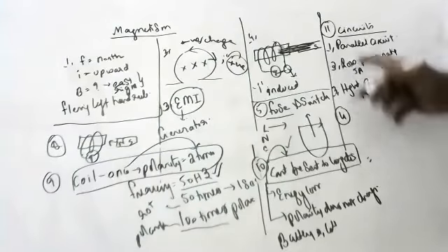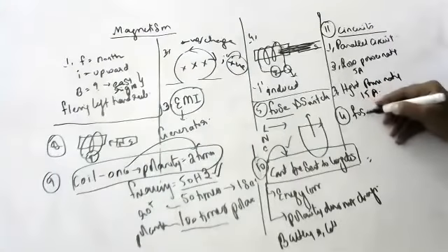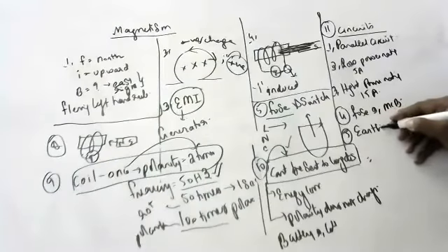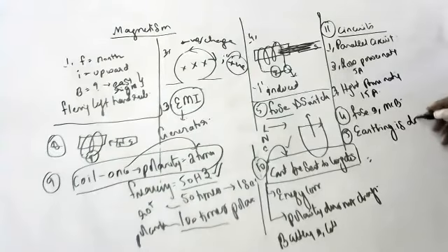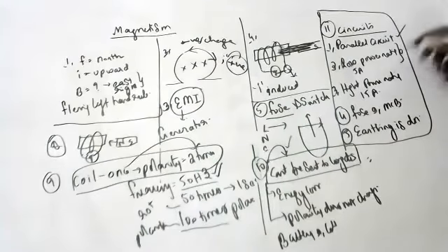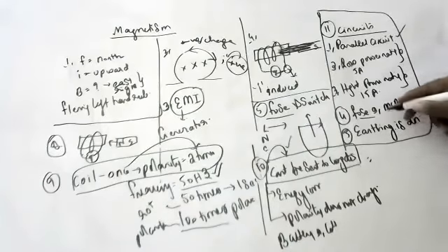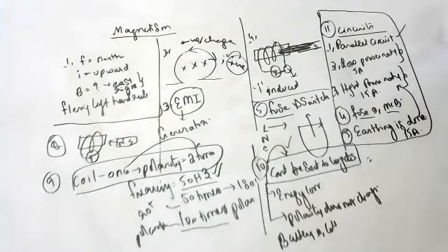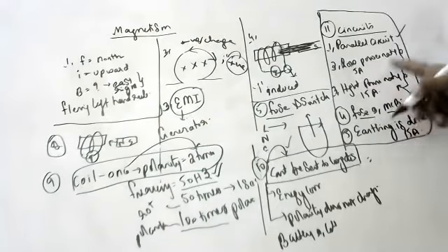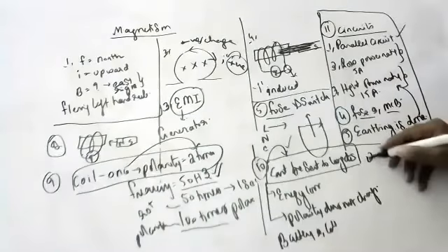Okay, children, and a fuse or MCB is used, and mainly earthing is done for the full circuit. Earth wire is used, which prevents shocks. Many points we can write, children, but these are the things expected. We will connect in parallel, low power rating and high power rating circuits will be there, a fuse or MCB is connected to all wires, and earthing is done for all the heavy 15 amperes rating circuits. Earthing and fuse are always kept for high power rating.